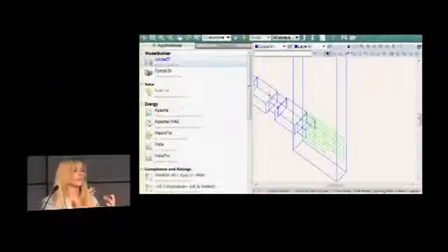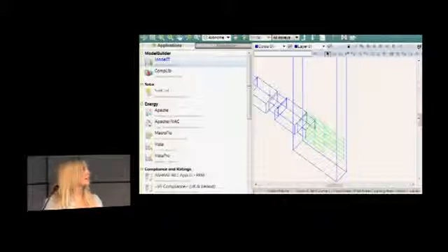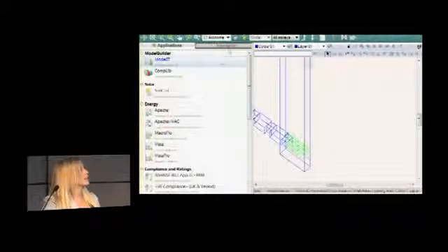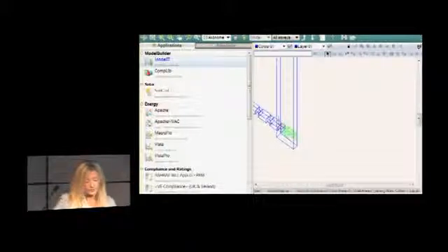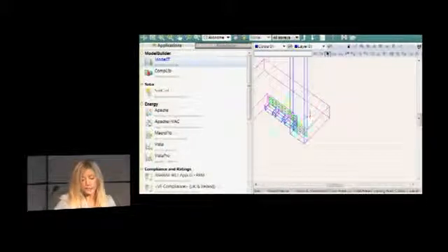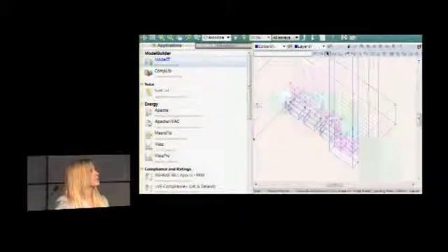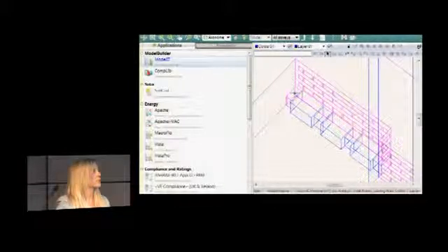So it's just a way of saving facade information and using it to pull information off of a BIM model or a space that's not behaving correctly or having problems. I save what the facade is like, and then when I go back in and draw that rectangular space behind it, I have the information from those windows saved on it. So it does allow you to keep your model and keep your details from that BIM model, even if the space is causing so many problems, like here where I can't separate the two for whatever reason. Then I can go in and use a trick like that.